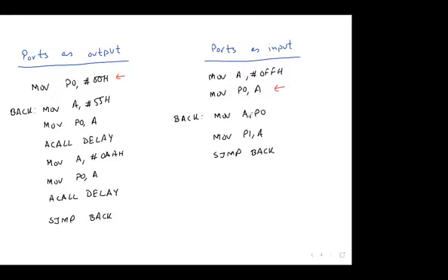Now look at the code. What you are writing is move A, P0. So whatever device is connected to that port will give you the data that you are storing in the register A. After that, what you do with that instruction is totally up to you or up to the designer. In this particular example, whatever data you receive from port 0, you are sending it back to port 1, and then we again jump back. Okay, so now if you have any question in these two examples, you can ask.